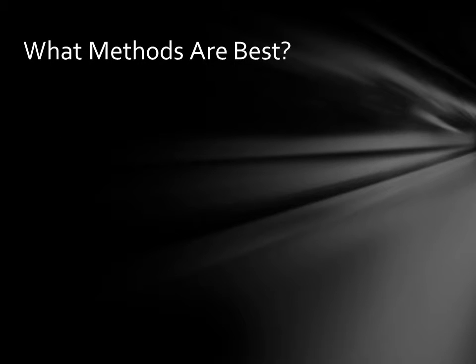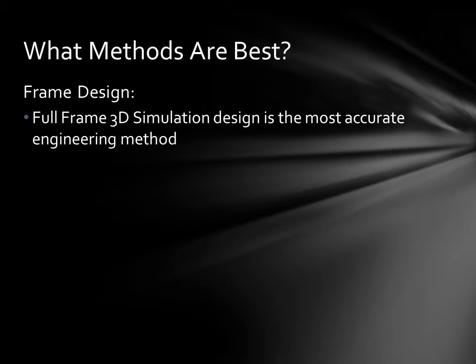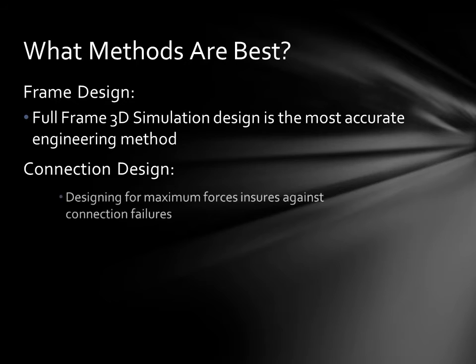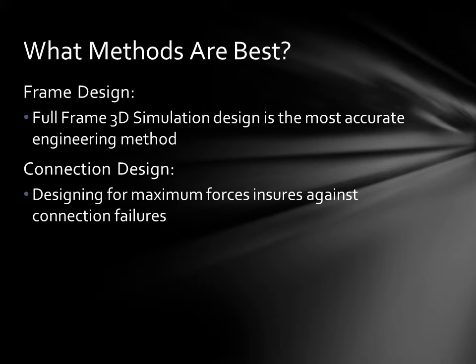So what are the best engineering methods when designing a screen enclosure? For frame design, nothing can compete with the accuracy of the full frame 3-dimensional simulation. For connection design, designing to maximum forces assures against connection failures.